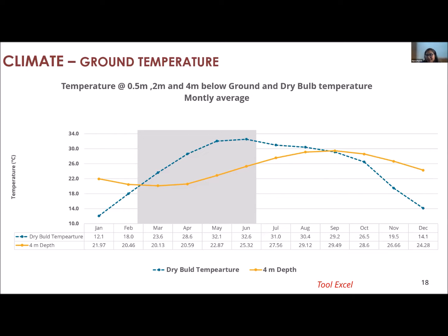Okay, so I would like to explain what earth air tunnels are and how they work. Earth air tunnels work where pipes are laid below ground at a certain depth, say at 4 meters depth, and air is blown through these pipes, at times actively, or there is an inlet for the air. The pipes, which are in direct contact with the ground, cool or heat this air through conduction. At times, earth air tunnels can be used for both heating as well as cooling in particular spaces. Okay, we've got a lot of responses, and I will now end the poll.